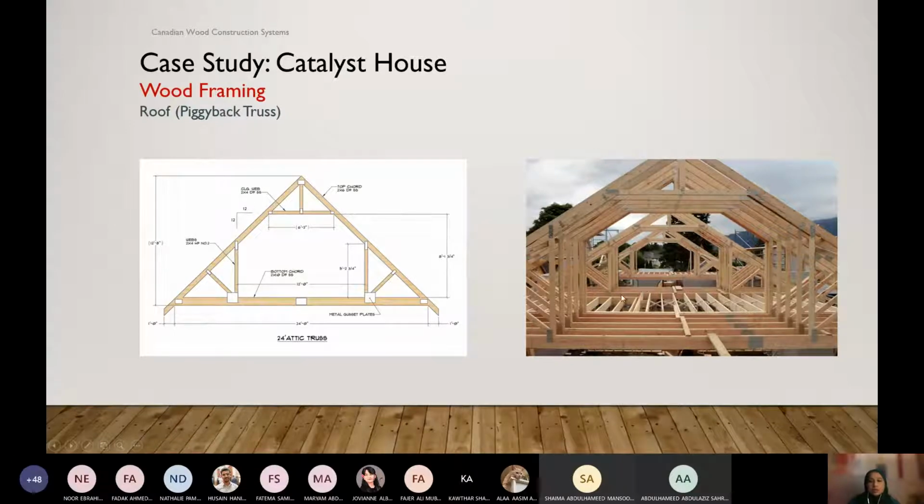There are tons of different options of trusses used. We can make a vaulted ceiling inside or any different sizes and shapes. That's the advantage and beauty of doing them in the factory, the engineered trusses, and they're very strong. For the trusses, the spacing in between them is mostly 24 inches from center to center.